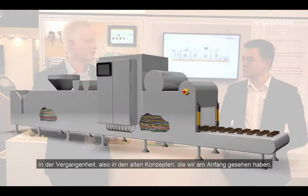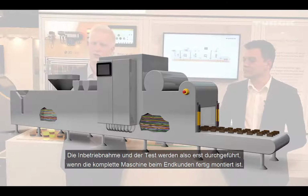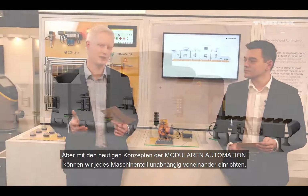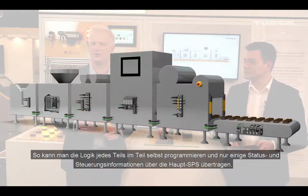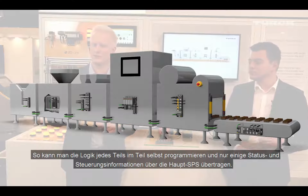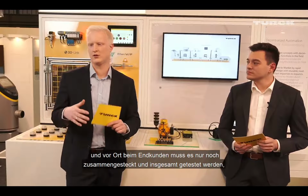So in the past, with these old concepts we see at the beginning, everything is connected and wired through the main cabinet and programmed in the main PLC. So the commissioning, setup, testing, everything could just be done when the complete machine is fully assembled at the end customer's plant. But today, with these modular automation concepts, we can set up each machine part independent from each other. So you can program the logic of each part in the part itself and just transmit some status and control information through the main PLC. So each machine builder can test his own part of the machine before it is delivered to the end customer. And on site at the end customer, it just needs to be plugged together and tested in total.